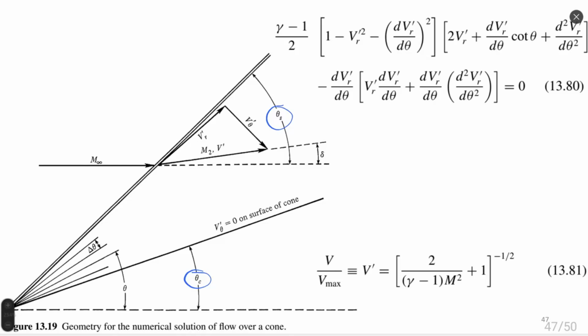These two angles, theta s and theta c, are the limiting angles where flow parameters change. Outside of these angles, we have no flow, or we have constant, uniform flow. For example, inside the body we know that flow doesn't happen, and outside of the shock wave, at M infinity, we have all the freestream flow properties.